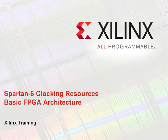This module introduces the clock generation capabilities in the Spartan-6 FPGAs, including its new DCM functionality. It also explains its global and I/O clock routing resources. This module also provides some recommendations about getting the most out of these clocking resources.